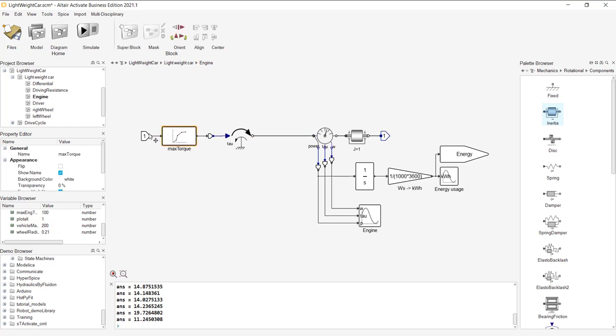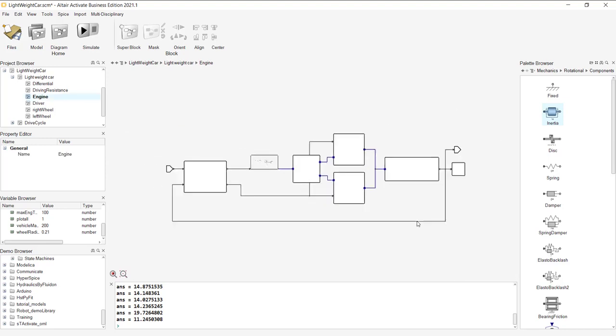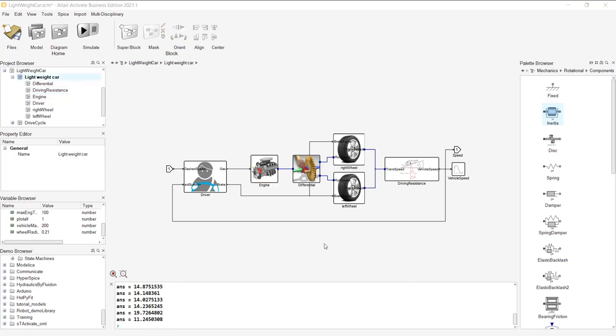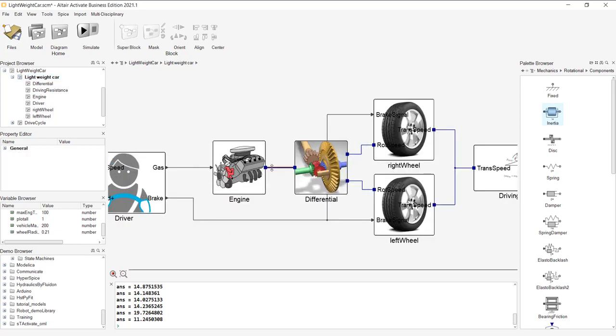And a lookup table here. So we have our accelerations coming from our gas pedal, which is going into a lookup table, which is an acceleration versus torque table. So from that, then the output of this will be our torque applied. So output from our engine subsystem, we have our rotational velocity of essentially the drive shaft between these two blocks here. And our rotational velocity signal enters as input into our differential.